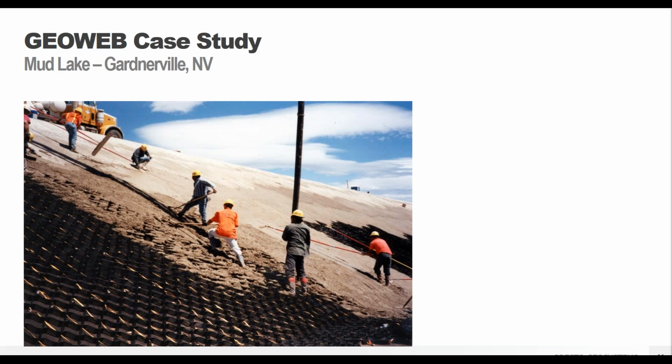So you don't have to bring in a tremie or one of those elephant trunks or anything to try and pour the concrete into each individual cell. You can have it as a mass at the top of the slope and then bring it down to the toe. That's easier. So there's a couple different options for installation, and if you do have questions about that sort of thing, it's something that we can help with.